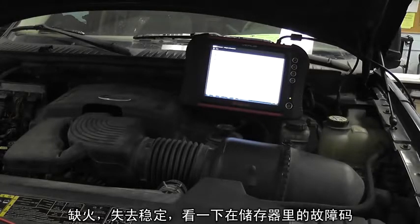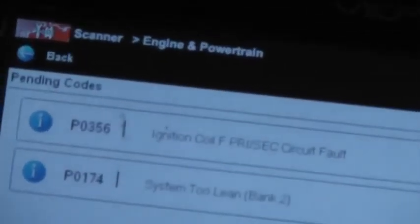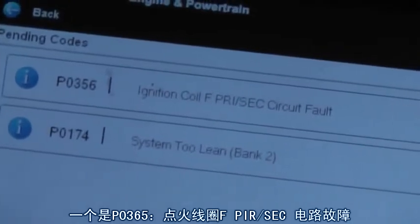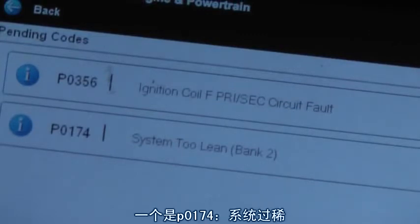So misfire, we have a constant miss, and the trouble codes that we have in memory, zoom you in on this real quick. We have two codes that we're worried about. We have a P0356, which is ignition coil F, primary/secondary circuit fault, and a P0174, system 2 lean.